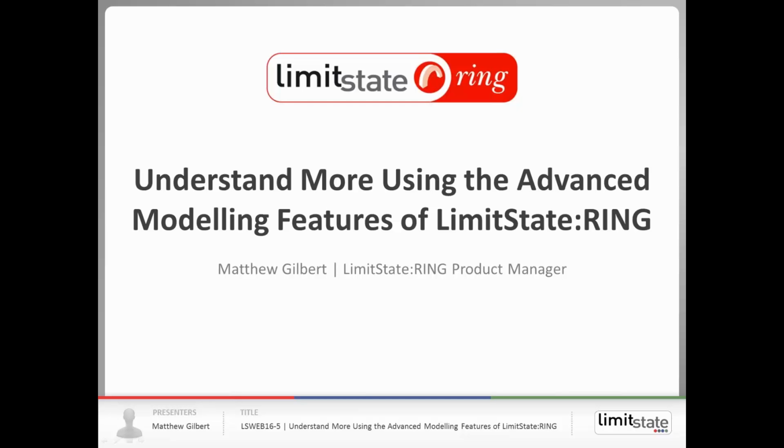Matthew Gilbert. The session is going to provide you with an insight into some of the less well-known features of our Masonry Arch software, LimitState Ring, such as how to diagnose the likely causes of existing transverse cracks, how to identify potential load paths under service loads, modelling specific defects such as partial ring separation, and also how to model the presence of discrete reinforcement.